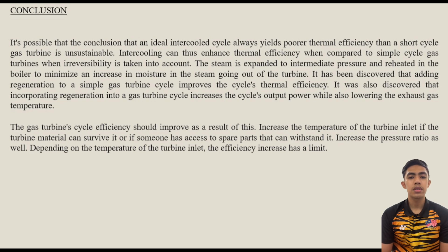The gas turbine cycle efficiency should improve as a result of this. Increase the turbine inlet temperature if the turbine material can survive it. Increase the pressure ratio as well, depending on the turbine inlet temperature. The efficiency increase has a limit.